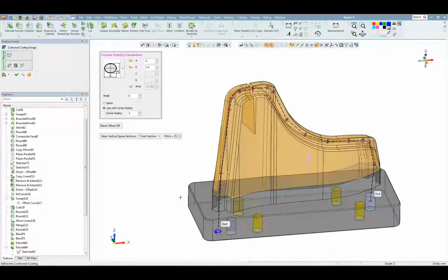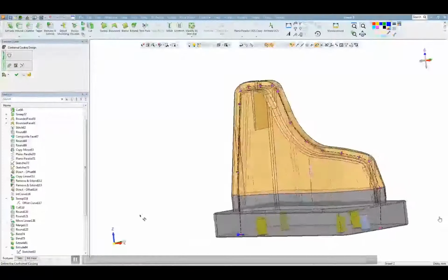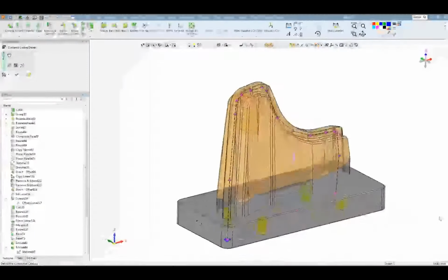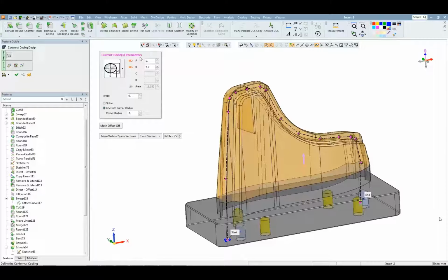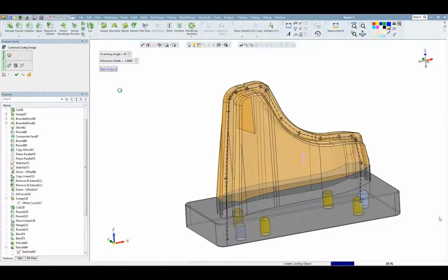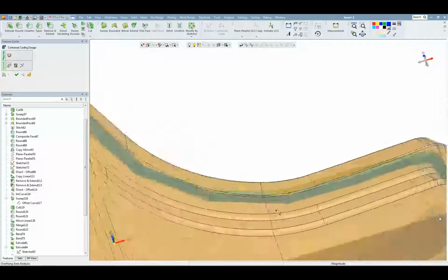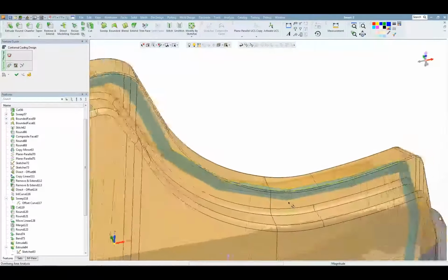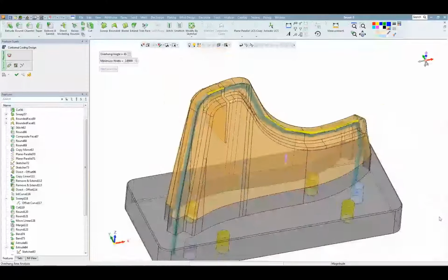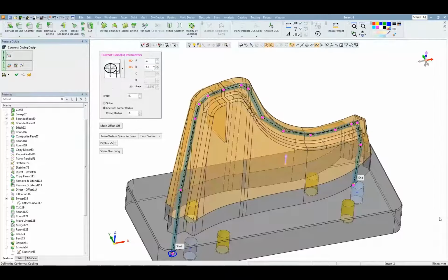So a quick demonstration of the cooling tools for version 15. We are looking at an insert here. We're looking at the cooling design tool with regards to creating a line and corner radius of the part here. We're doing a quick analysis for the overhang limits of this cooling channel. We can see it's highlighting the areas that are above the overhang limit set at 45 degrees. So this gives us a very good feedback for the 3D printability of our insert here.